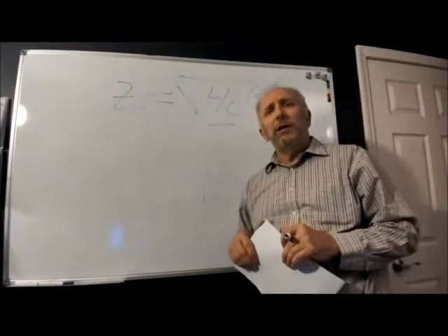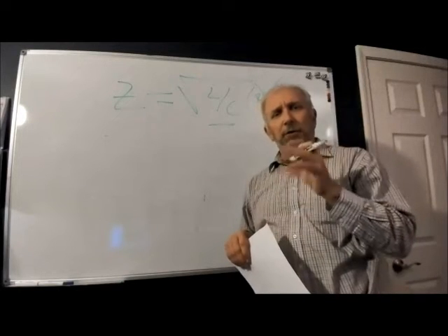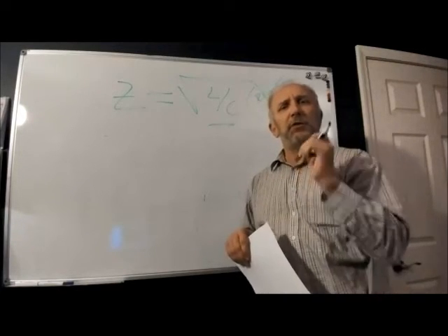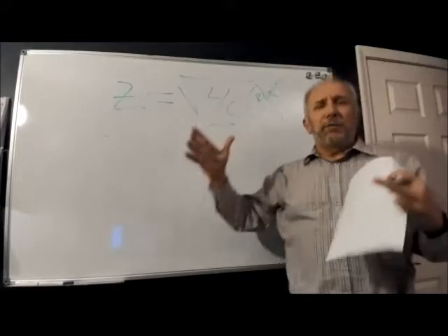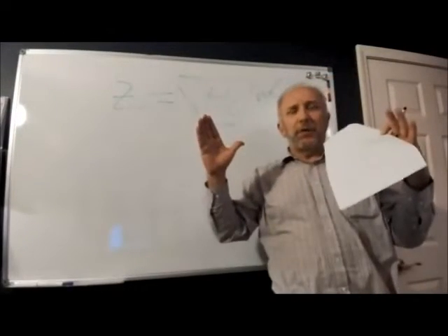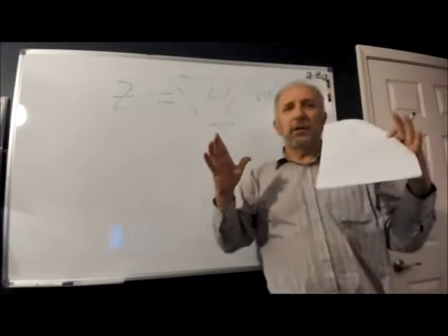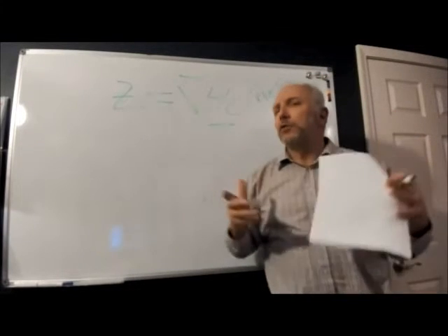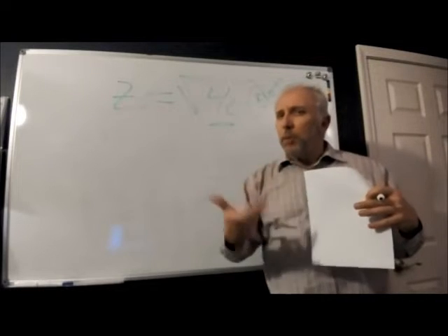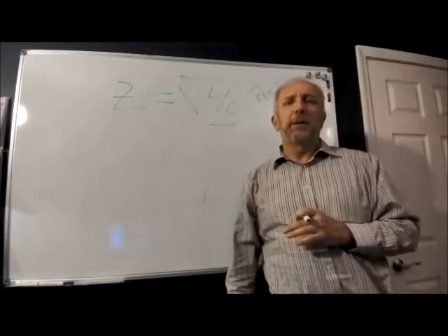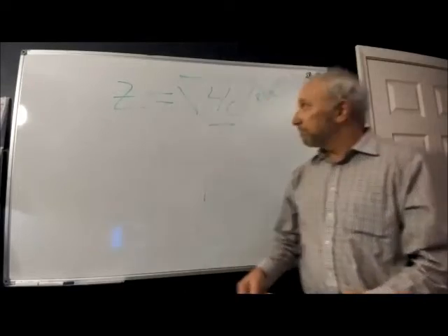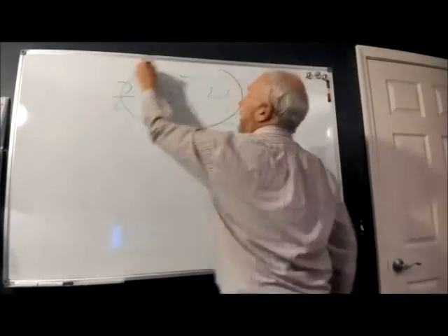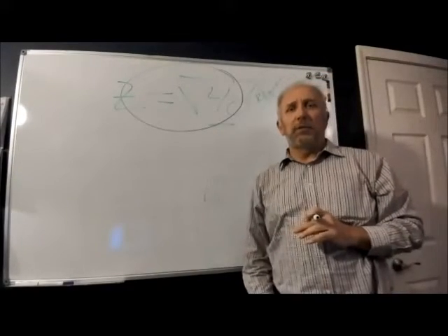Yeah. You know what? You're right. Although if you think about it, it doesn't matter, because if you normalize, get rid of that per meter or per inch, it doesn't matter. So you have a piece of transmission line, with X number of Henrys in loop inductance and X capacitance for a fixed length, it doesn't matter. Normally we would say for some length, but it doesn't matter because we've taken that lumped element and we have now distributed that. Okay, so the important concept is the characteristic impedance is equal to the square root of L over C.